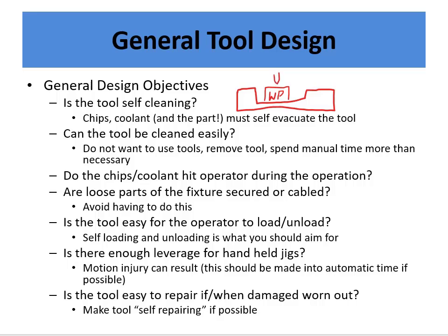It's some sort of drill on some CNC machine. Here's our little drill with little flutes, and it's going to drill a hole in here. And let's say we have some coolant nozzles that are coming down and spraying coolant all over here. This design is going to make it so that this area gets full of coolant, right? And full of chips, and they're going to flood in this area.